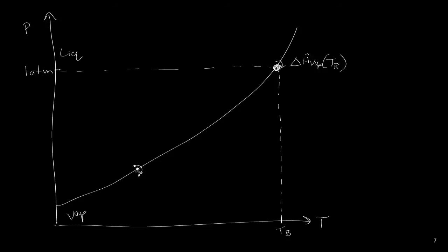So what we have to do is reroute ourselves to go through this data point here that we actually know the conditions. And we can do this relatively straightforwardly by calculating enthalpy changes. So the first step would be to go from our saturated liquid state here and start to transition from whatever the temperature and pressure are at this state over here to this condition. So here we're at some arbitrary pressure P and some arbitrary temperature T. So the first step is we would go the delta H going from the system pressure to 1 atmosphere.